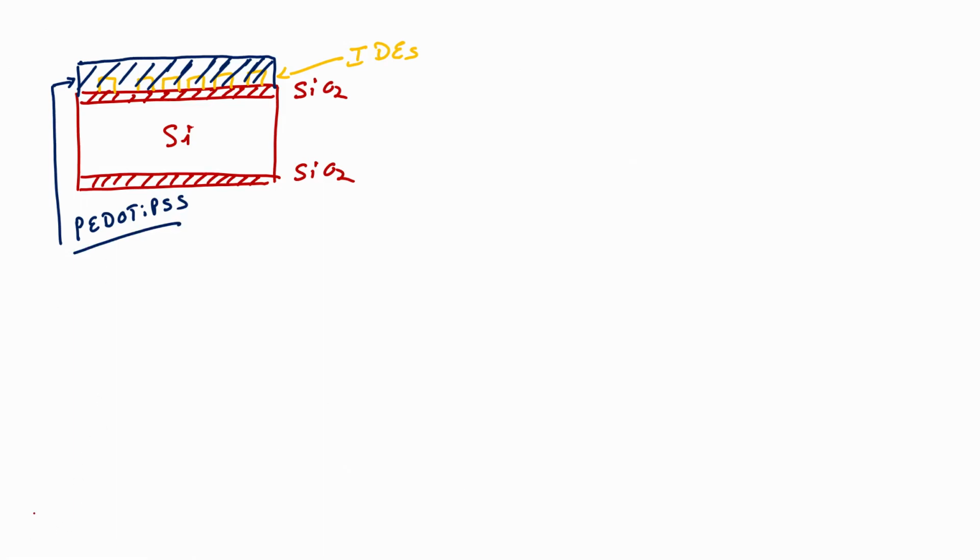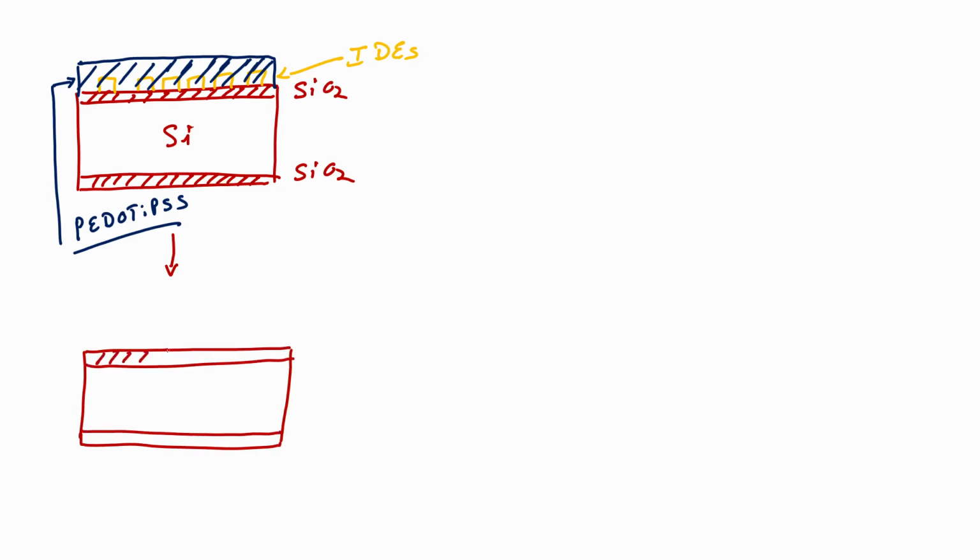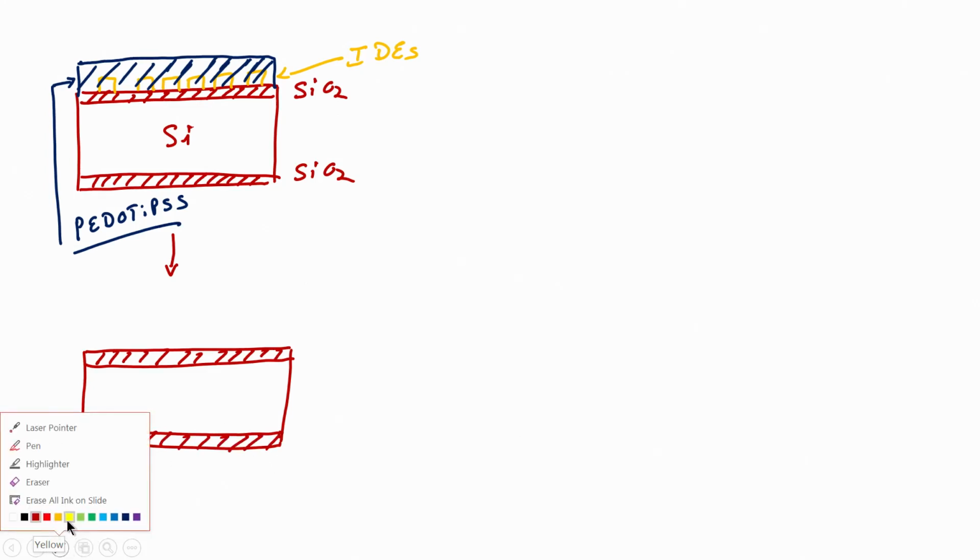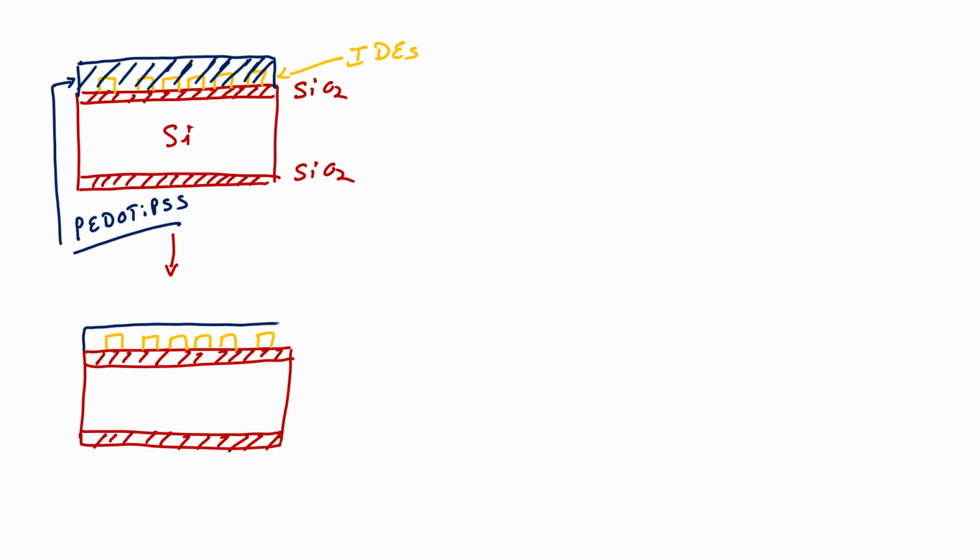The next step here is: I have an oxidized silicon wafer, with oxide on the bottom part and oxide on the top part, with interdigitated electrodes on top of it, right, and then on that we have PEDOT:PSS which will act as a piezoresistive material, and we need to pattern this material, right. So, this is my piezoresistor or piezoresistive material. There is chrome gold inside.